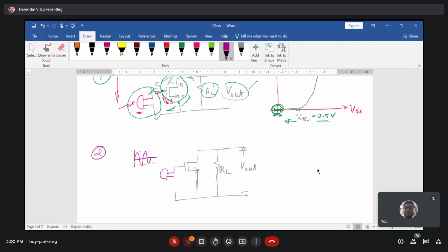Along with that, we try to connect a DC biasing, a certain voltage, and that voltage is equivalent to the threshold voltage of the device. What we have done is that we have an analog signal superimposed on the DC signal. This is the setup we are creating at the input side. In comparison with your previous figure, we just added a DC biasing, and our analog signal is superimposed on the DC, and the remaining things are the same.